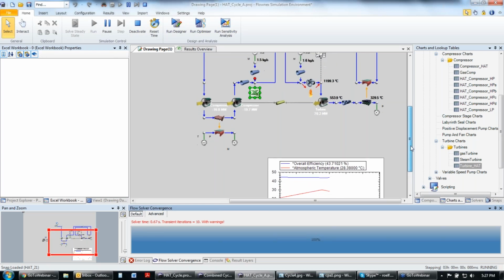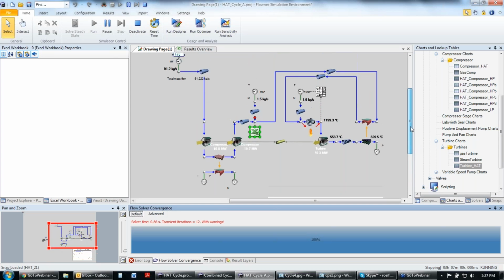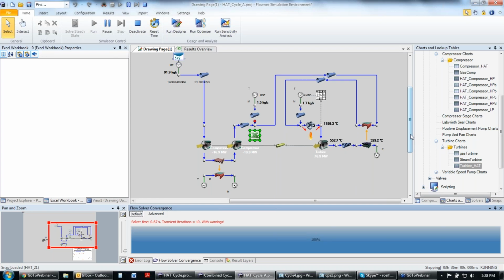So just again, this is a very, very basic transient scenario, and you can set up anything, turbine trips, compressor trips, and you'll be able to simulate the behavior of the whole system with the inertia of flows, with the inertia of temperatures that is in our geometries of the heat exchangers, and this will help you to get a real picture of what happens in the network.